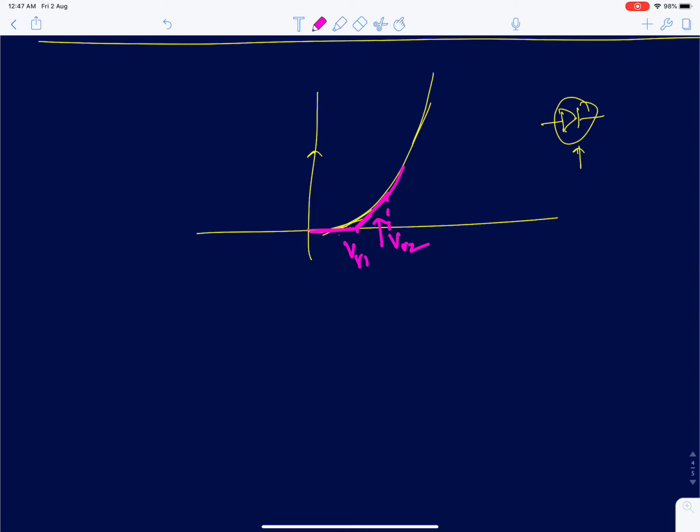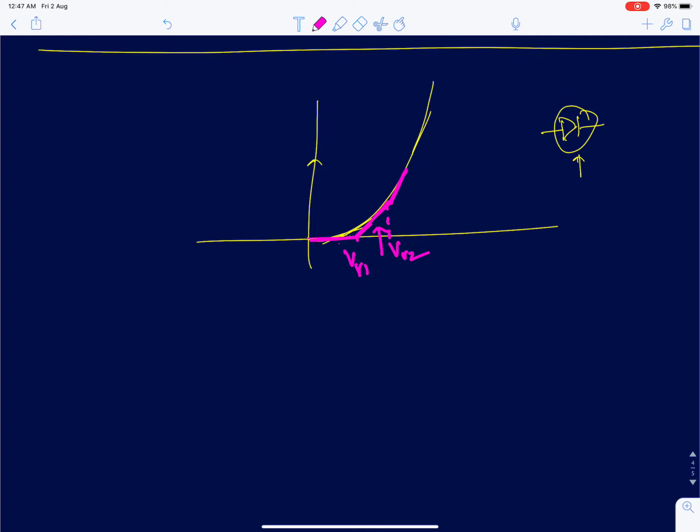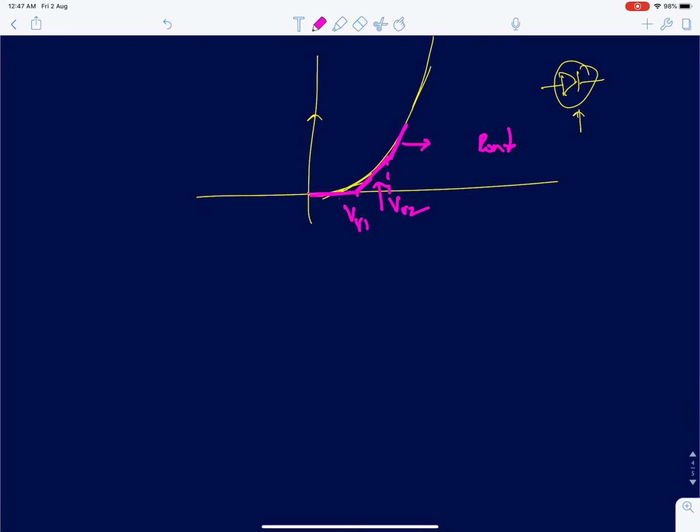After this range, I want the slope of this line to change, to slightly increase. So what does this mean? If the slope is increasing, R on is reducing. Let's say I'm interested in modeling it in this entire region, and I can better approximate it by two piecewise linear curves.